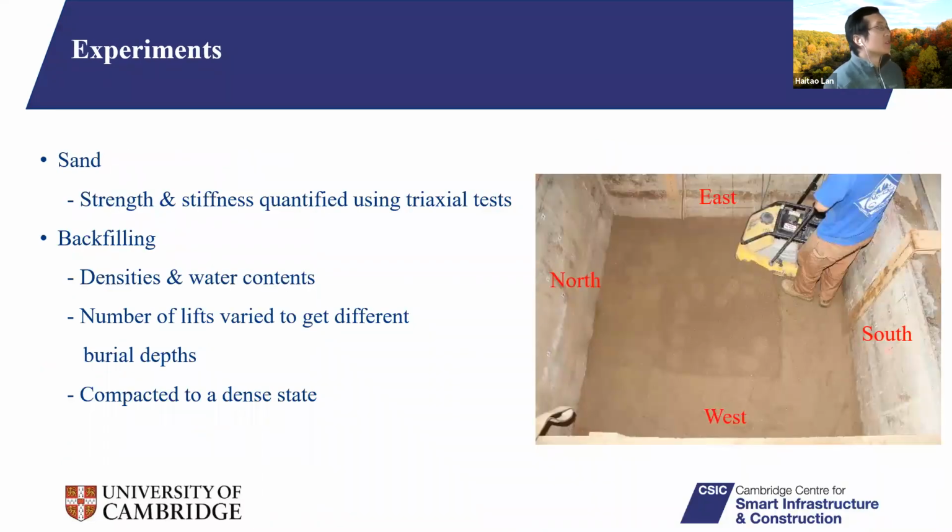Sand was used in all these tests, of course. The strength and stiffness have been qualified using triaxial tests. During backfilling, we measured the densities and water contents in each test and each layer or lift. And we controlled the number of lifts or layers so we could get the different burial depths. Sand was compacted into a dense state by using a small vibrating plate compactor, as shown in this picture.